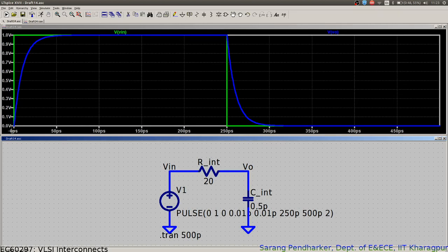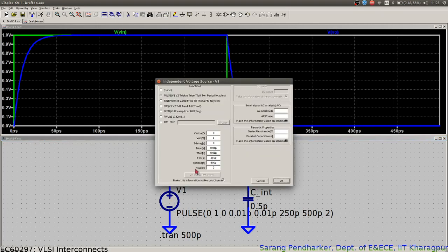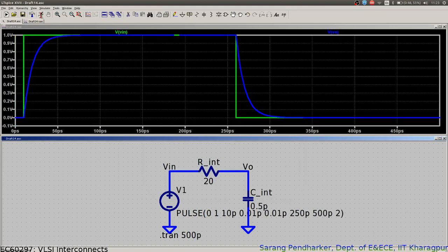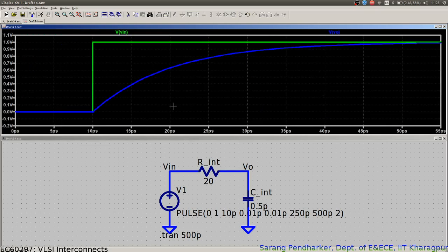Right? Now I also want to find delay. So what I find easier many times is to include an offset in my input signal itself. So if I create an offset in my input signal and then I run, so my on starts from here, so it's easier for me to track the delay. So let me zoom into this part and look at the delay.